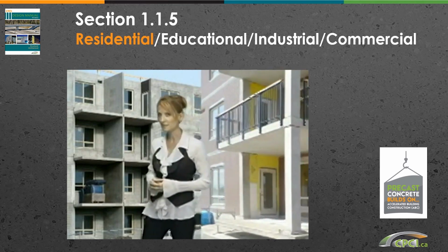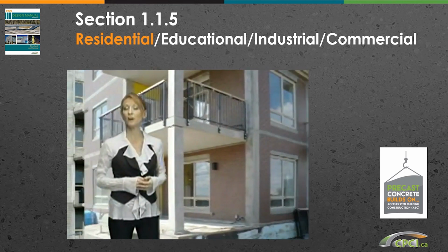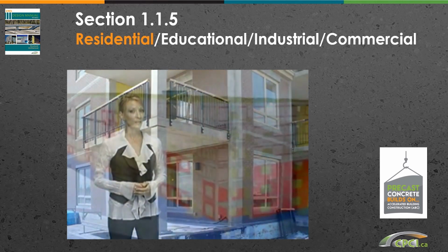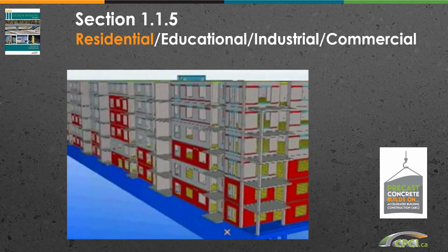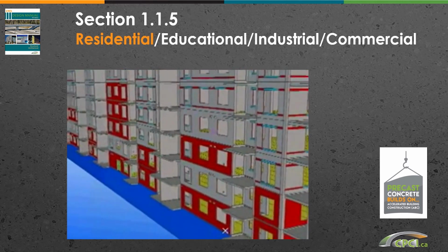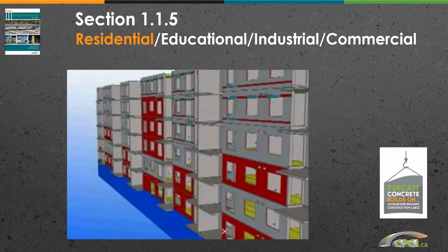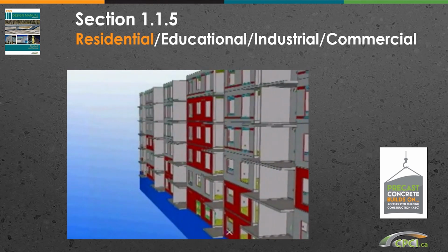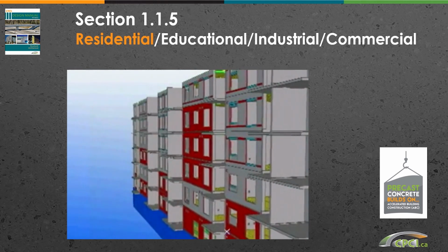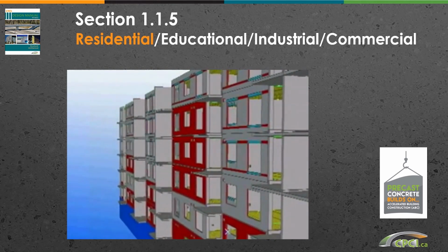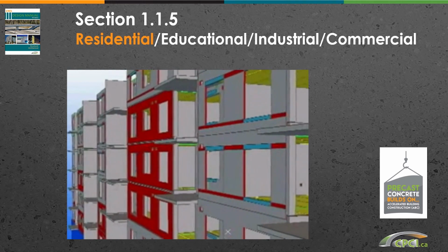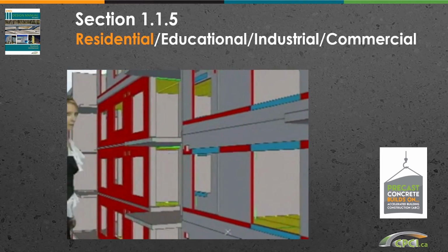The precast panel system also provides the exterior architectural finish, creating a red brick look balanced with flat accent areas. An innovative framing method created by the design team allows the wall system to be staggered, providing a look that has traditionally been difficult to achieve using precast components. This method also allows the balconies to be cantilevered from the building surface, differentiating these buildings from previous precast solutions.